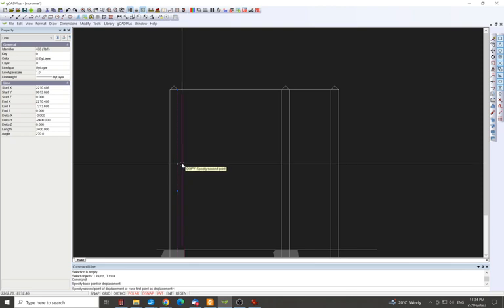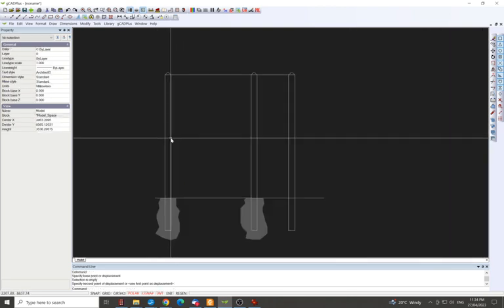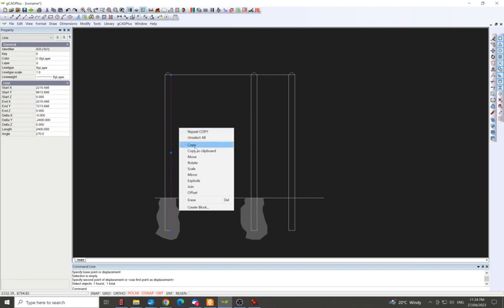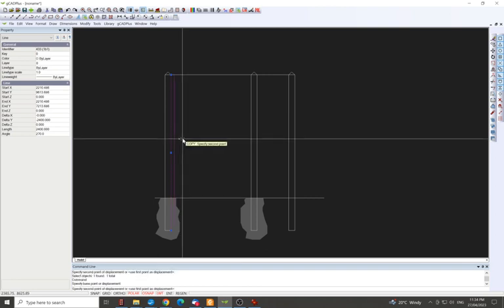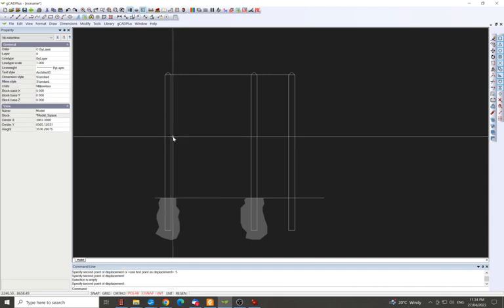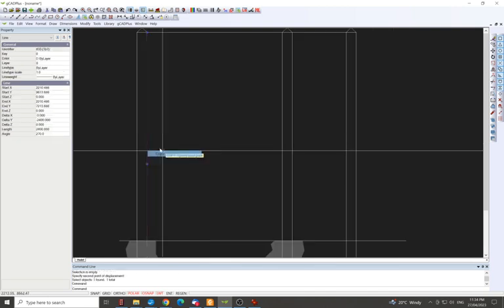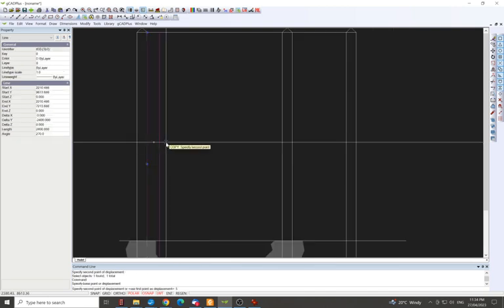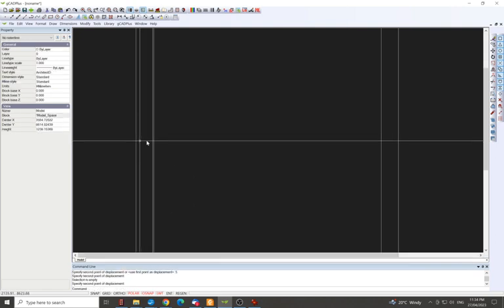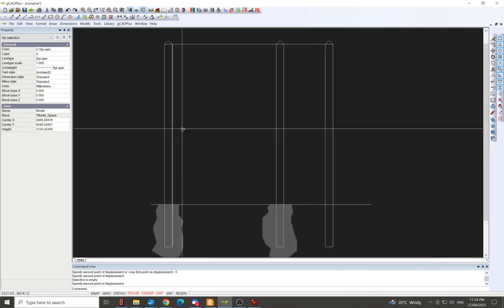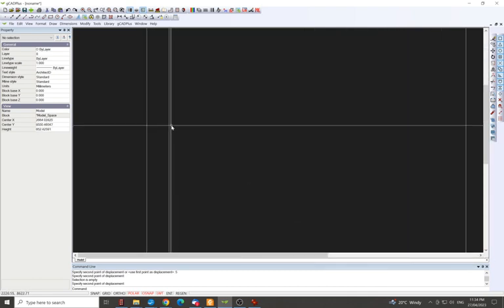What I'll do is I'll just take this line off this fence, just left click on it, click copy, click again, move it out, and I'll type the space in, which is going to be 5mm. So just 5, enter. Oh, hasn't done it. Okay, something's gone wrong there. So copy 5. That's done it now. See, so there's your 5mm, and that's our hinge gap we've got there.